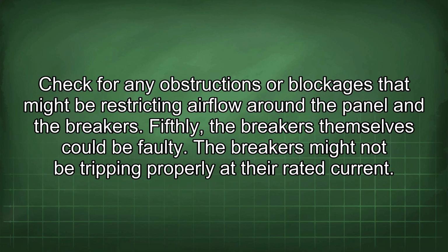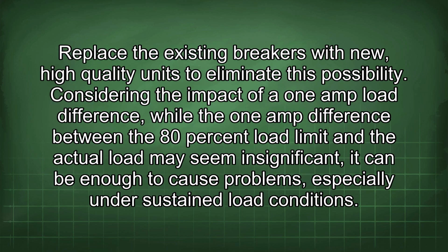Fifthly, the breakers themselves could be faulty. The breakers might not be tripping properly at their rated current. Replace the existing breakers with new, high-quality units to eliminate this possibility.